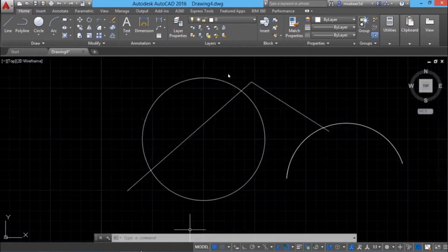Otherwise, it won't work. Next, I'll talk about the units command. Before we start any drawing, we have to set a proper unit. Basically, we create drawings in decimal and imperial units. In AutoCAD, when you work, we actually create the drawing in the true dimensions. Later on, while going for the plot, you can specify a proper scale to scale down the drawing or to scale up the drawing. So let's go to the units command.